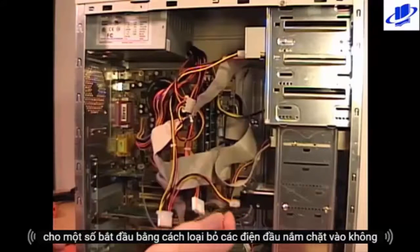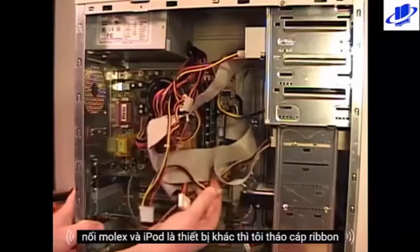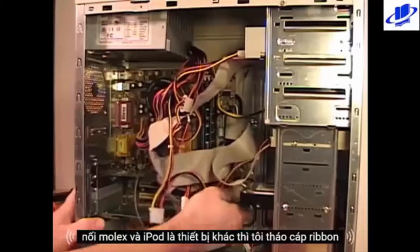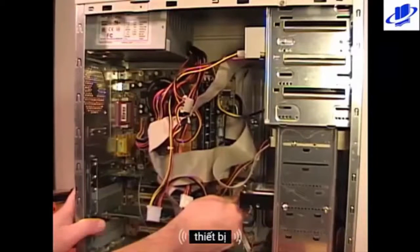First I'll begin by removing the power lead, gripping onto the Molex connector, and then I pull it out of the device. Then I remove the ribbon cable. I grab the ribbon cable close to the connector and then pull straight out from the device.